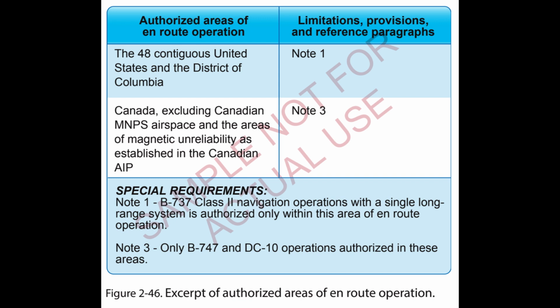Commercial operators planning to fly off-airway routes should have specific instructions in the company's OpSpecs that address en route limitations and provisions regarding en route authorizations to use the GPS or other RNAV systems in the NAS. The company's manuals and checklists should include practices and procedures for long-range navigation and training on the use of long-range navigation equipment. Minimum Equipment Lists, MELs, and maintenance programs must address the long-range navigation equipment.